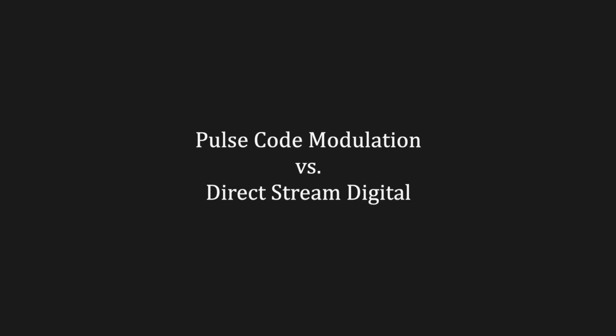All CDs use PCM, pulse code modulation, to store sound, but Super Audio CDs use a different system called Direct Stream Digital, DSD. In DSD, the audio signal is turned into a stream of single-bit pulses using a method called sigma-delta modulation. Most standard analog-to-digital converters, AD converters, also use sigma-delta techniques. They first raise the signal's sampling rate, upsampling, then use a decimation filter to lower it again and convert it to PCM, 44.1 kHz for CDs, or up to 192 kHz for DVD audio and Blu-ray.